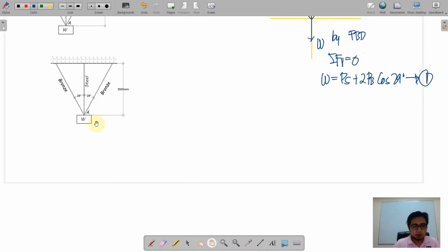As a matter of procedure, we have discussed that we are going to unpin this joint at A. And of course, it's obvious that these three rods will just stretch out. So let us have the corresponding stretches of these three. By the way, we cannot compute the deformation yet since the forces are unknown. The steel bar will just stretch out along its vertical axis. Same is true with the bronze rods. So they have symmetrical orientation.